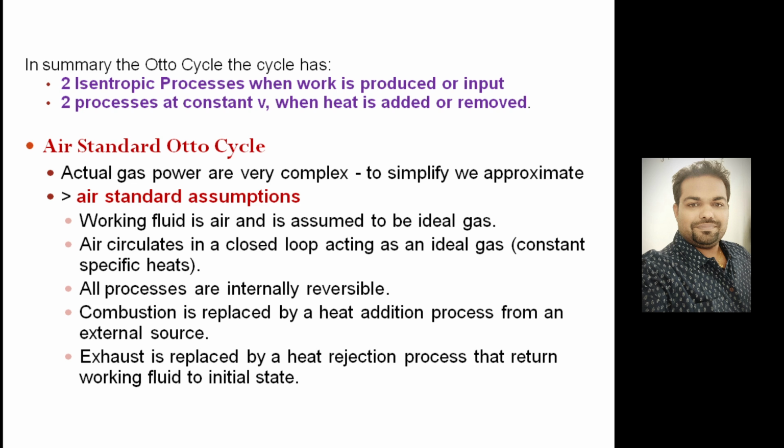So over the period of time in the second cycle, it will be very difficult to carry out the combustion because it is basically a combustible gas having more carbon percentage, right? So less oxygen is present, so burning will not be that smooth and you will not be able to get the required combustion temperature, so performance will deteriorate. If you are going for the third time, then there will be zero oxygen present, so combustion will fail.